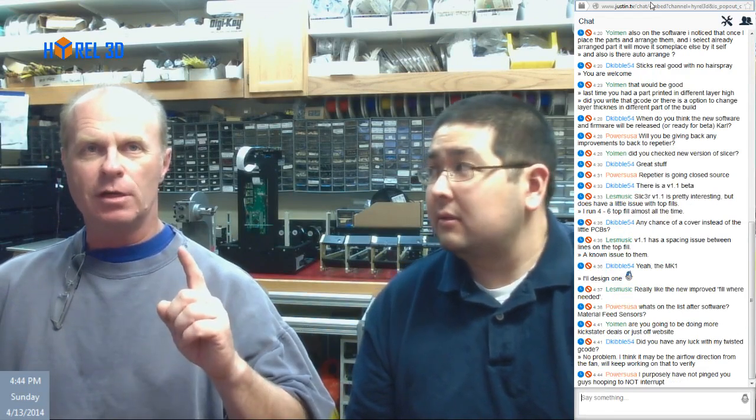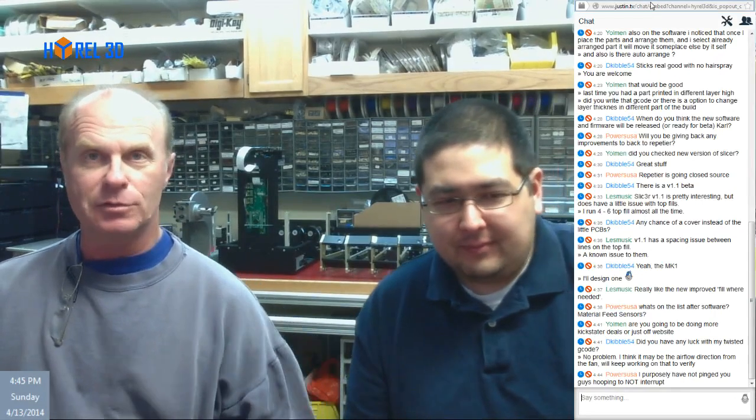That's one thing that popped up this week I'll share with you guys. Davo was printing like a fool. It was amazing. And then he comes to me and says, this darn thing won't print. It keeps dropping temperature. And I said, really? Let me look at the code. What was happening was somebody accidentally put the hotbed temperature of 100 degrees in the hot head, so the M104 became an M140. A little less dexterity there. And so the machine was doing exactly what it was told to do.